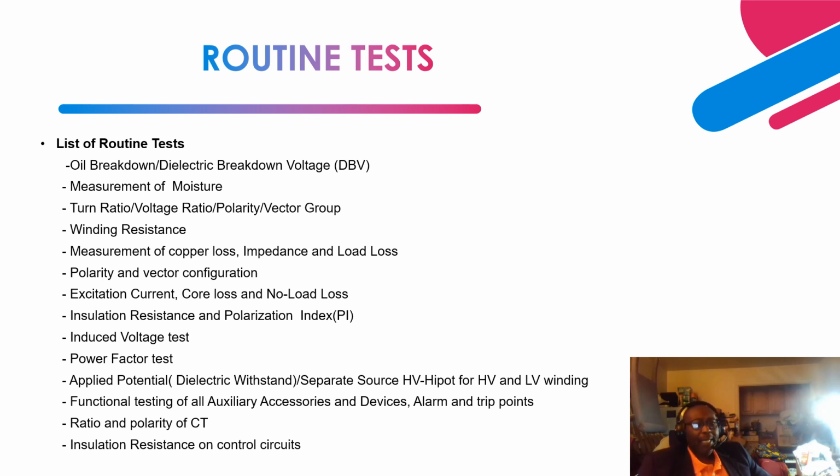So what you do is compare the excitation current that is flowing in the external legs, phase A and phase C, with the phase B leg of the core. The excitation current in milliamps flowing in phase A and phase C should be the same, and the one flowing in phase B should be different from what is flowing in phase A and phase C.